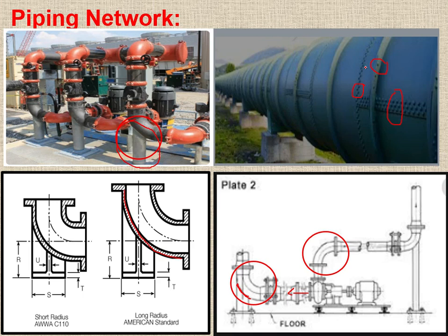because of the change in momentum, because of the pressure force, there are stresses on these rivets. If these rivets are not strong enough, what will happen? There will be possible leakage from these points, or it may break from here. So that's why, whenever the fluid flows through the pipe, all these joints come under stress,